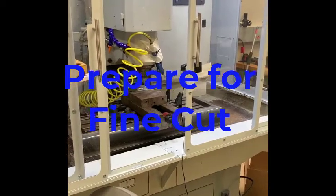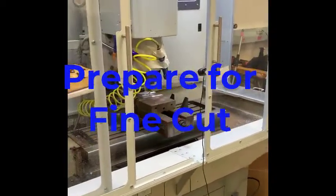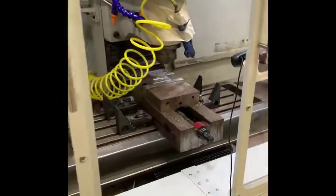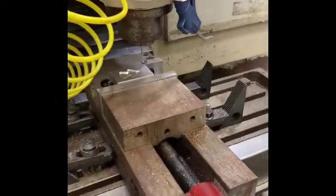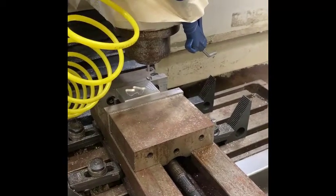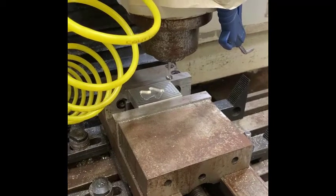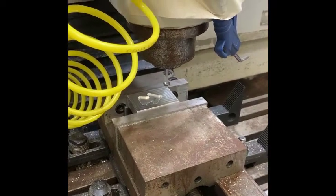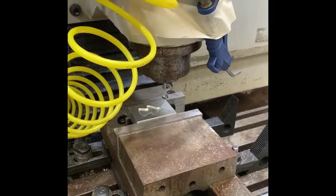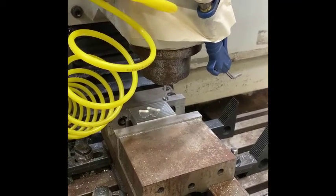We surfaced our mold half, and then we did a rough cut, as you can see on Patrick's screen. So we need to reset the Z axis, or the Z0, because we don't have an automatic tool changer, so we need to manually set up the Z. We're going to walk you through that process, and then you can start machining some little details out.